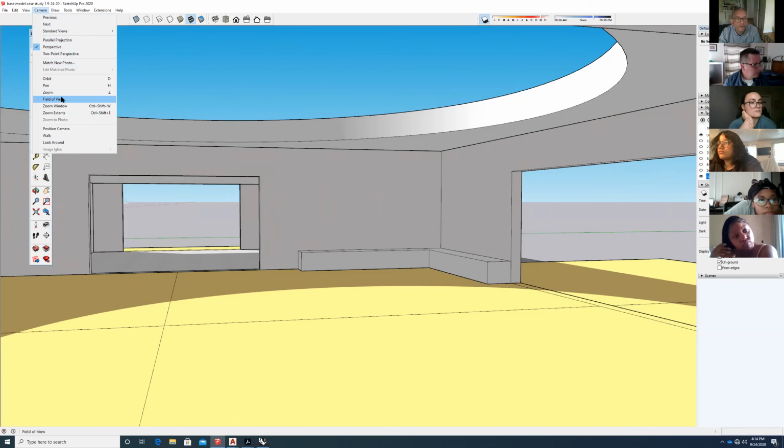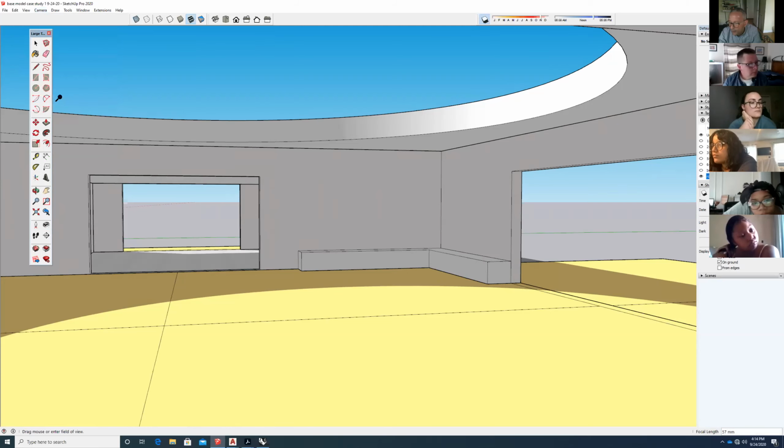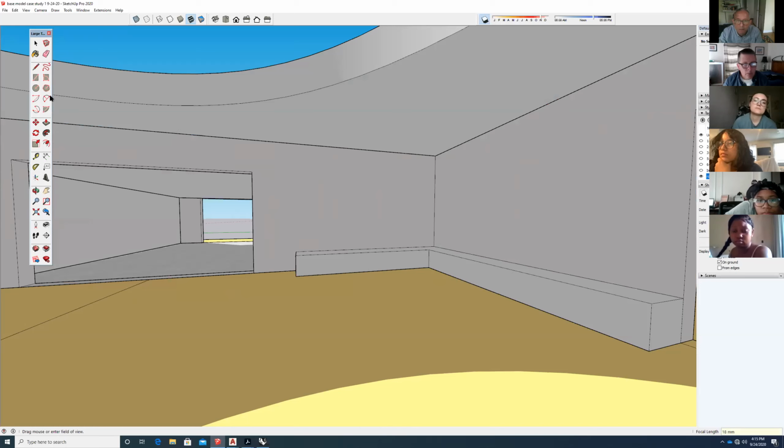And I'm going to go to field of view. Right now, for some reason, it says 57 millimeters, which is something we really don't want. Standard views are around 50 millimeters or 35 millimeters, but we want to see a lot. So actually the number goes down. I know if you haven't done photography, these numbers, but what we want is I want to type in 18 mm.